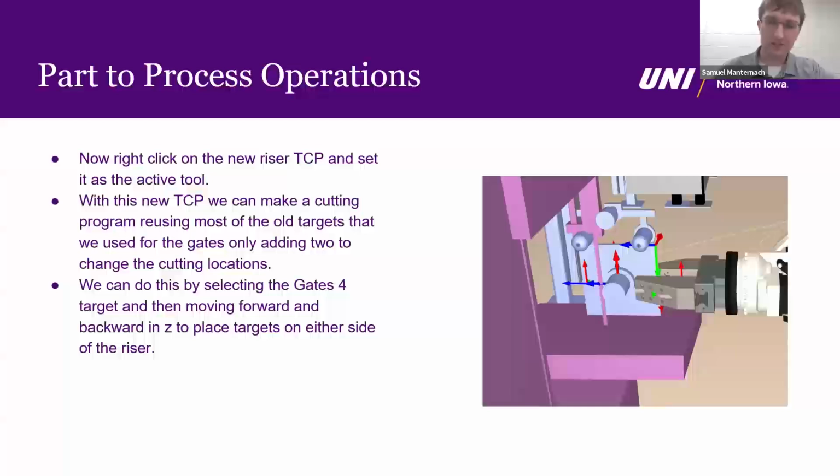With that location set, you'll have it actually embedded in our bandsaw blade, because that is the location of the center of the riser. So in order to get our 2 cutting locations, we're going to want to move our part a little backward and forward to get our start of cut and end of cut. All you'll have to do is select your robot in the dialog box, and then we'll move backward in Z to locate our part for the start of the cut.